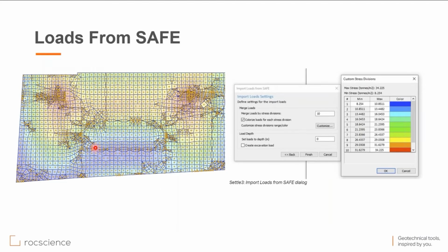Also, we can import loads from SAFE, which is a finite element program that will give a huge number of loads and vertices, or nodes, for these loads, and you can interact with SAFE backward and forth so that you can reach the required spring moduluses for the foundation. So the structural engineer can use them in his structural analysis.